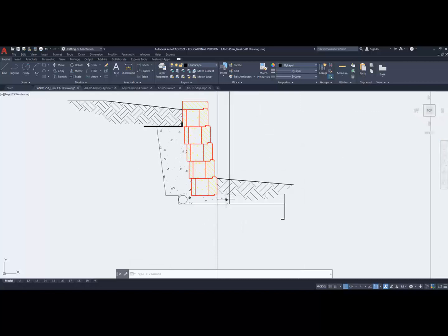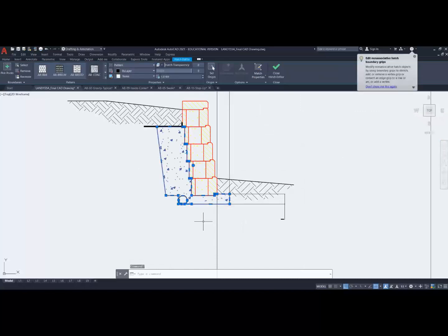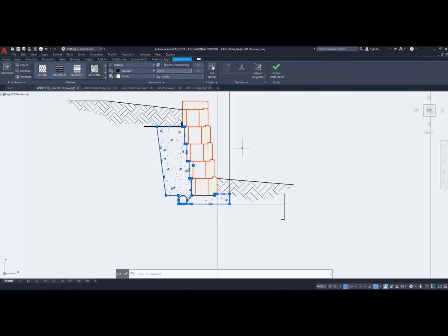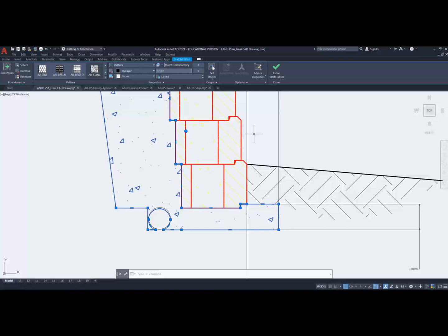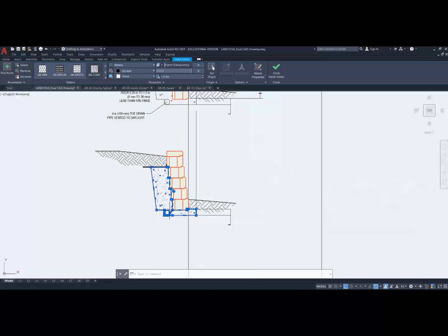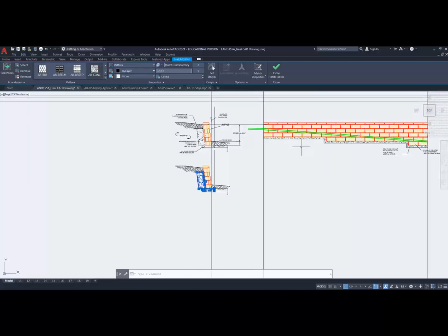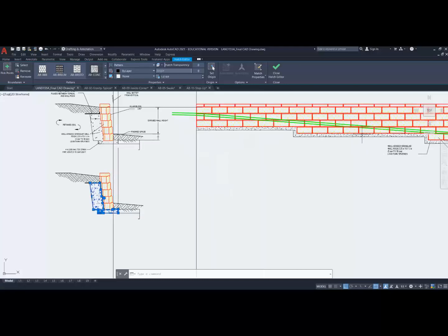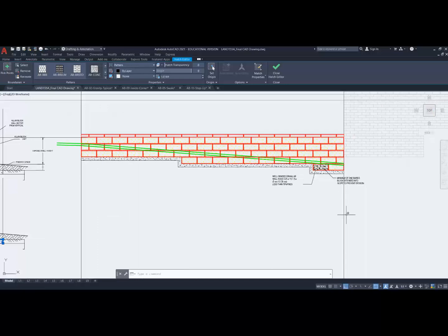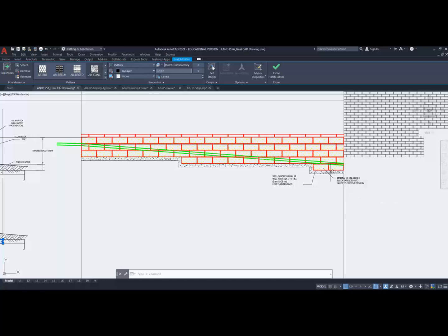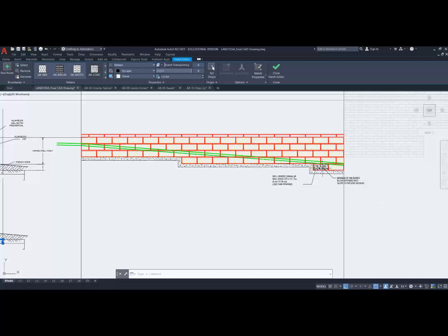So this stuff that's in here, once again, I'm questioning whether I should actually show or use their method of hatching or create my own hatch. Notice I've got a drain tile here. That drain tile is below the lowest block. If I bring the drain tile here, it will go towards the house, which is okay, but I got to provide some areas out here that tile can drain away from the house so that it isn't something that will drain to the house. So I have to provide an exit hole here for the drain tile.